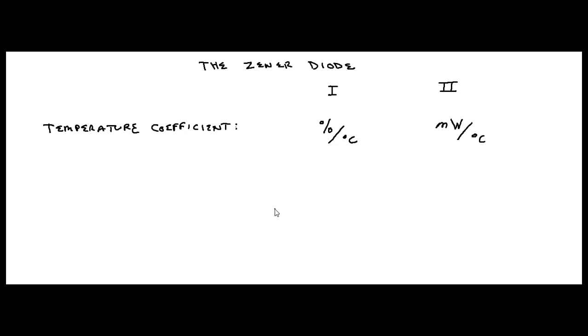So you can buy Zener diodes in many flavors. You can get them in 10 volt, 5 volt, 15 volt, with different numbers of voltages that you want. Okay? So the reason why you get them is because you want to hold something to a specific voltage. You don't want it to change, okay? So one thing that can affect the change of the Zener diode voltage is the temperature of it. So you have to think of the environment where it's going to be operating.